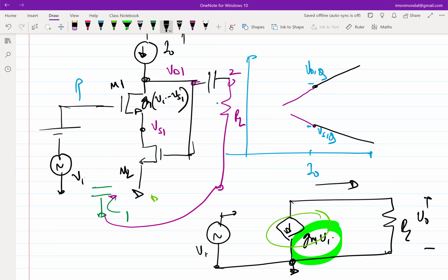Yeah. Correct. So ultimately, the whole point is, we would like to ensure that this behaves like a common source amplifier. His point is, even if I don't short the VS1, right? There seems to be, if an incremental current flows, a loop for the incremental, which is correct, which I agree, but it is not the maximum that we can get. So to get whatever the maximum that we can possibly get, we have to short VS1 incrementally.